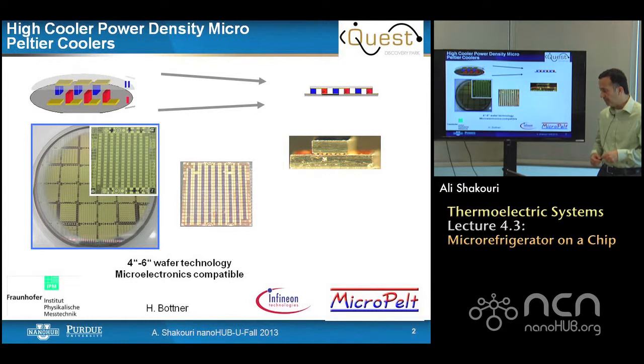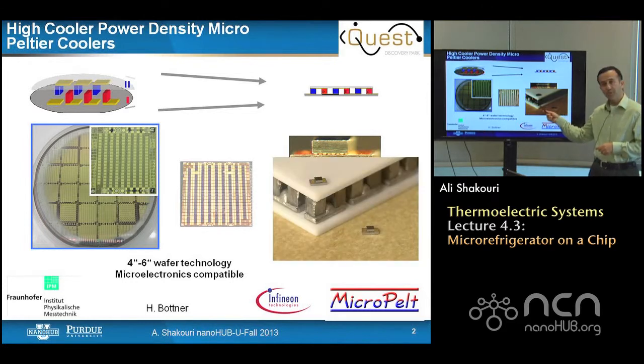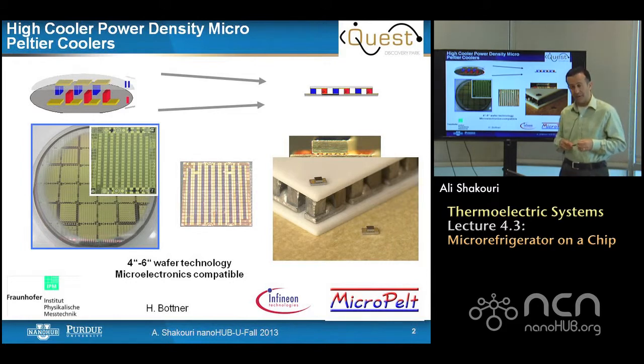If you take a thermoelectric module, today most commercial modules have thicknesses on the order of 1 or 2 millimeters. They have low cooling power density. One thing to do is make the same thing with the same material but tinier elements. The leg thickness scales inversely with the cooling power density of the thermoelectric. So if we make the leg 10 times thinner, if everything is ideal, the cooling power density of the thermoelectric device increases by a factor of 10.